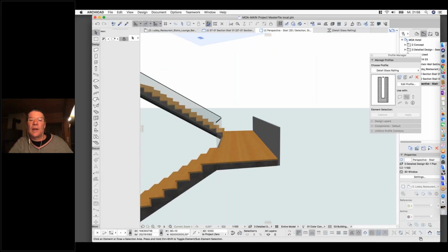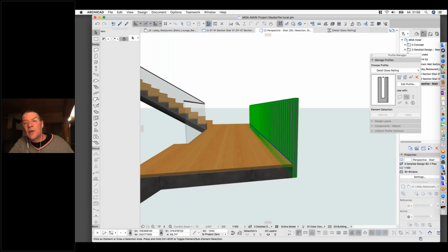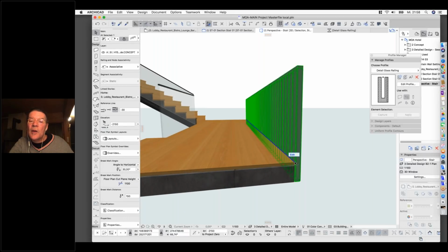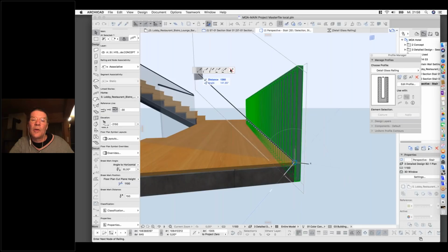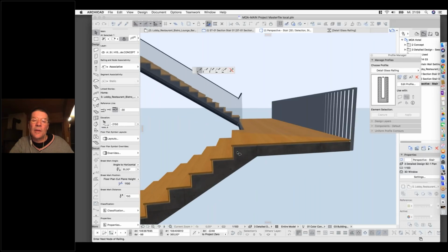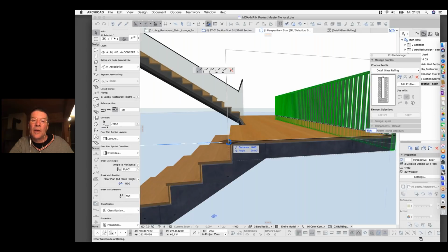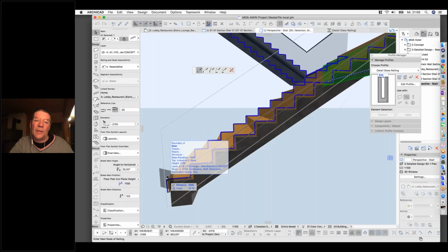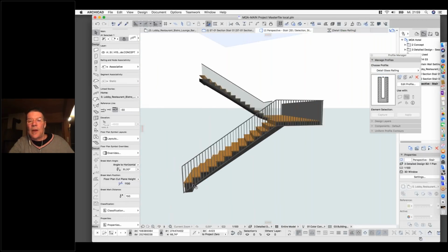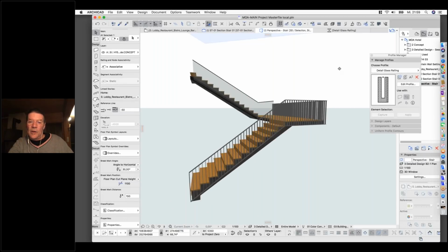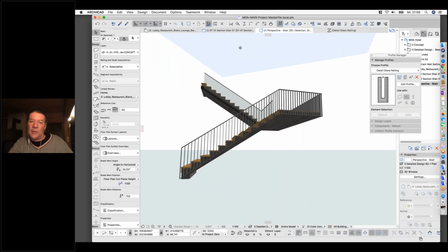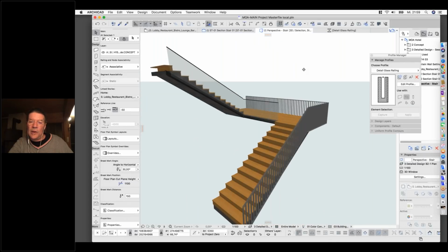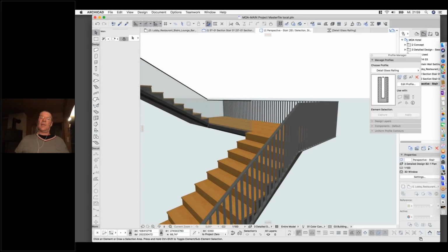And again, after exit, you can choose the one, and instead of adding, just go to the end of the reference line of your rail, click on it, and we are still in the drawing mode. And you can say, nice, I want to have the rail going to here, and now it's time to go down, like here. So that's the way, and you can see the setup was pretty good, because this rail is nice and smooth, and you can use it for detailing. I think I am through.